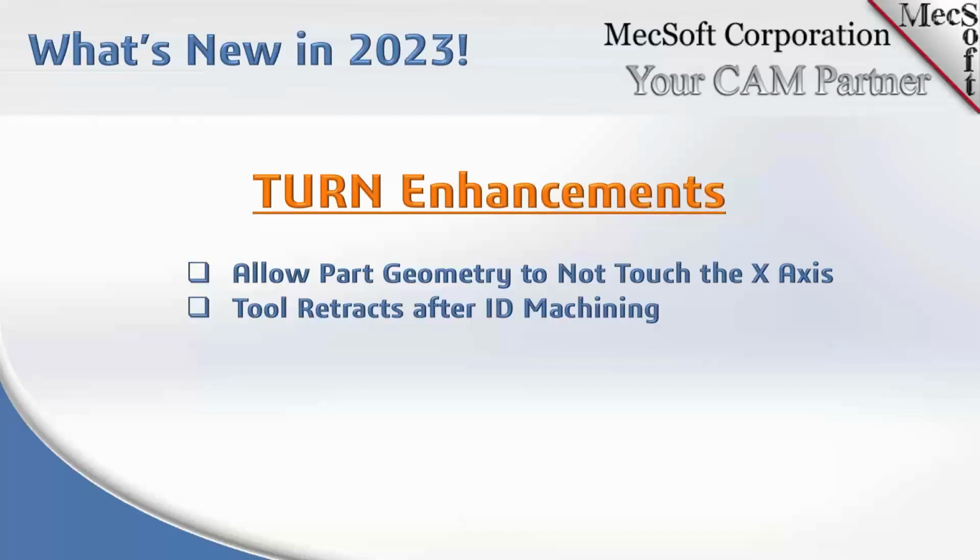And then we added some enhancements to retractions, and this comes in handy when you're doing ID machining, finishing, and roughing in an ID. Now we're retracting linearly back out to the clearance plane and not diagonally from the last cut point. I'll show you that in just a moment as well. If you use the turning operations a lot, you will notice that enhancement.